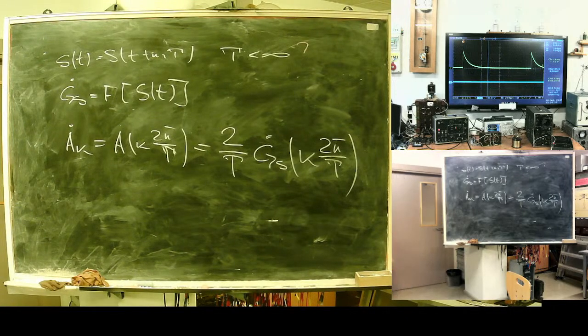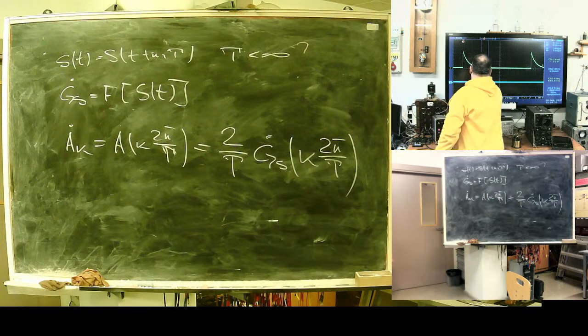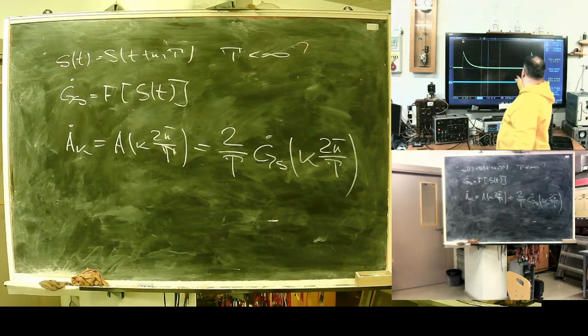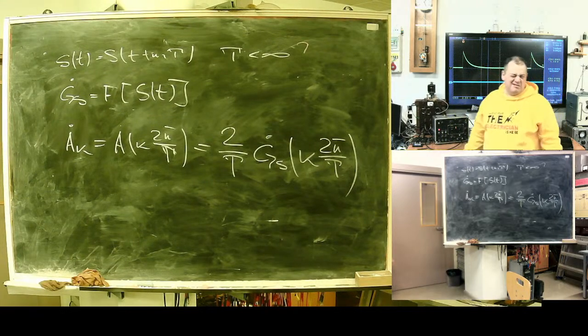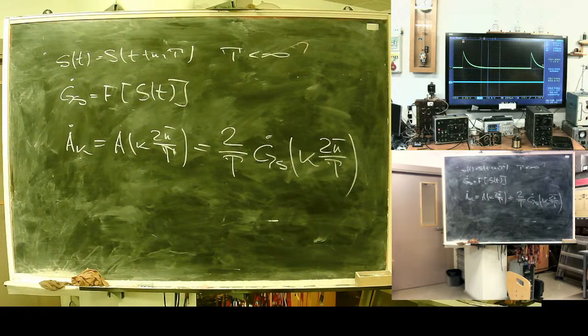For example, if here everything ends at 1, 2, 3, 4, 5, let's say in 10, it means 2 milliseconds. If I set the simulation time for 2 milliseconds and assume it's a period, I can create a Fourier law for a periodic signal with a period of 2 milliseconds. And within 2 milliseconds, the spectral function will give me the values of harmonics. It's a brute force approach, but it works.